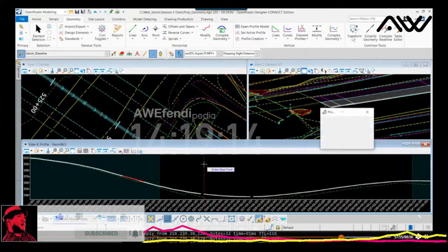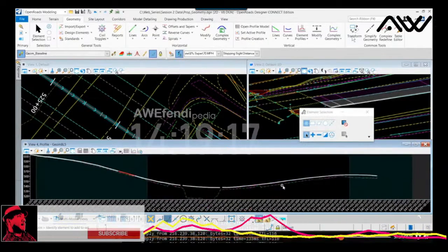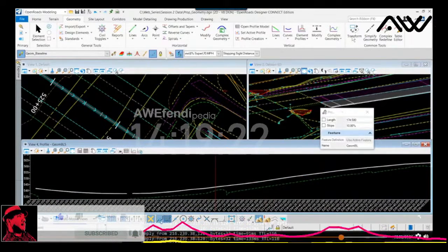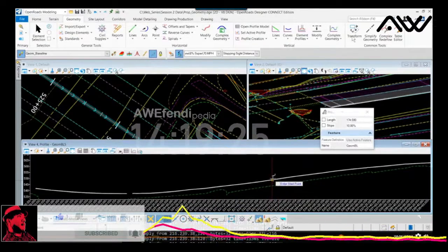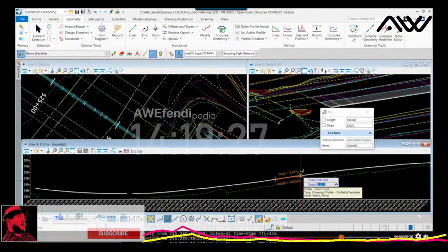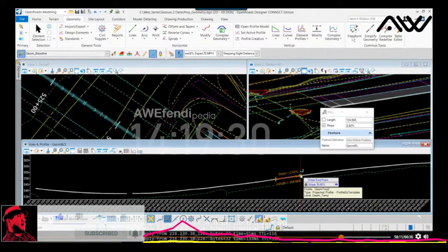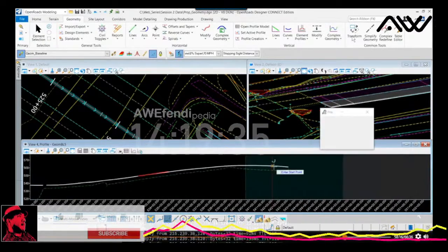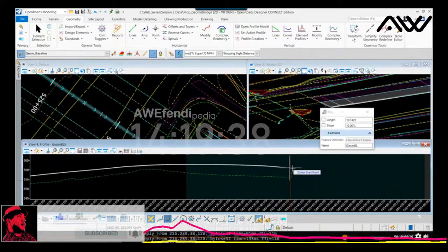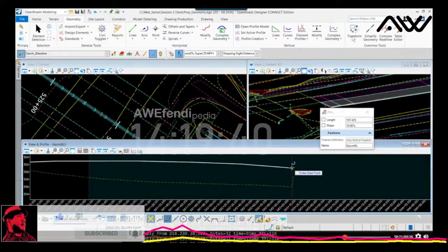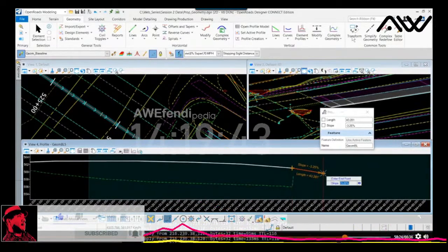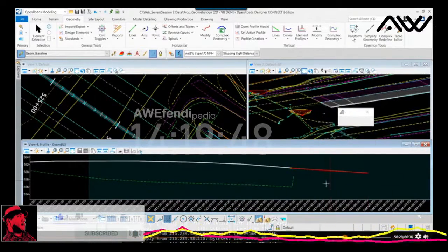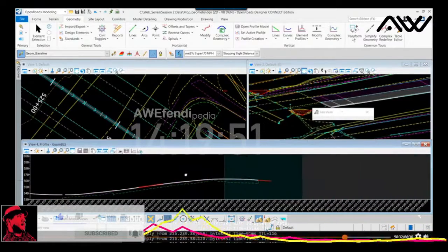And let's go to the next tangent area. Again, same process. I can follow along here. And the next section, we want to hold to a 3% grade. Okay. And then finally, on the very end, we've got just a small tangent. Since we end in a curve, let's jump. I'm going to snap there, and we'll make the last segment a minus 1.25. And place that. Now let's insert the curves based off of, again, our design standard that is being applied.